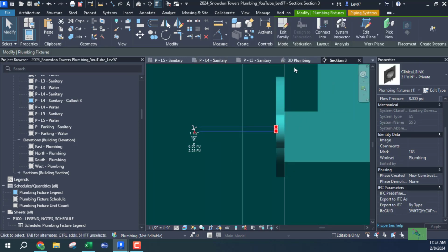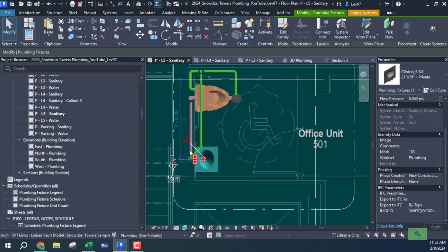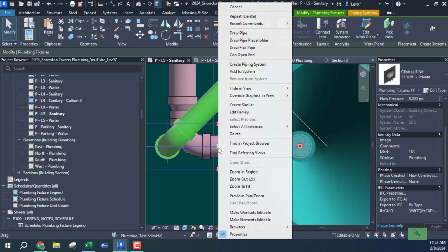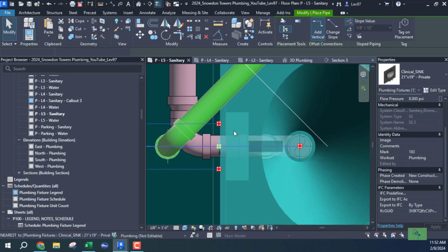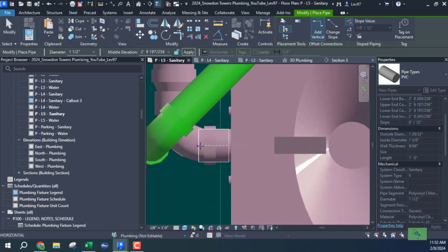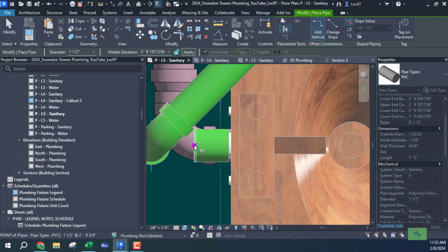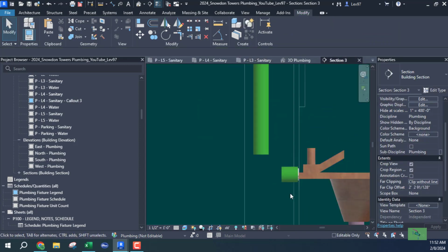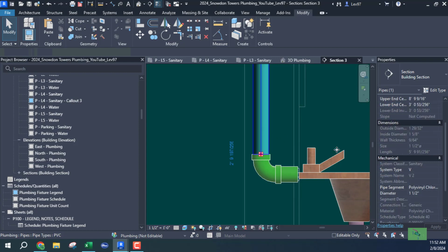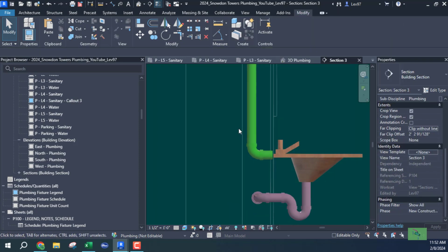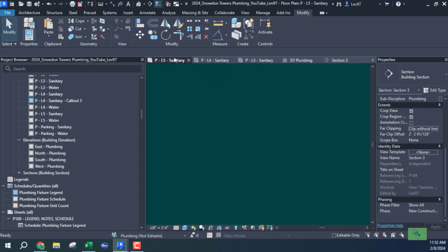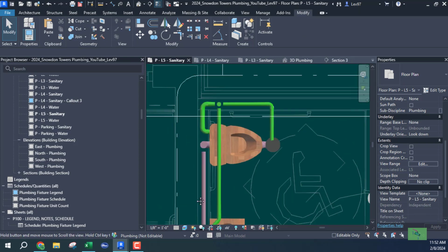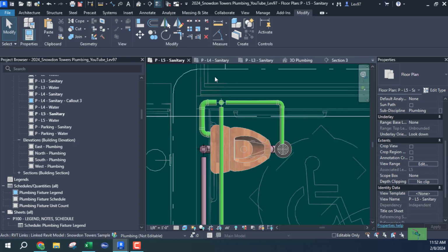One of these. Let's go up. Let's go 5. Make sure we get the vent, which is here. See what we get. Okay. I'm going to stop it about right there. Let's go back to our section and let's do a fillet here. Okay. And I'm counting fixture units again, right? 6, yes. Okay, 5. Okay, all of this connection.